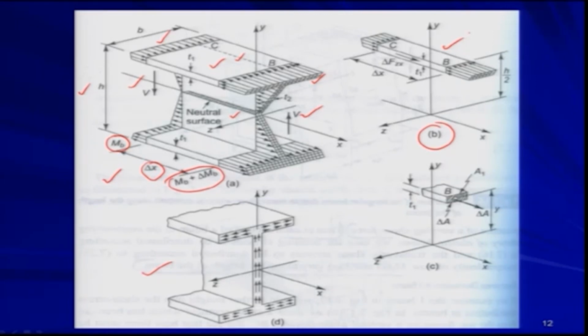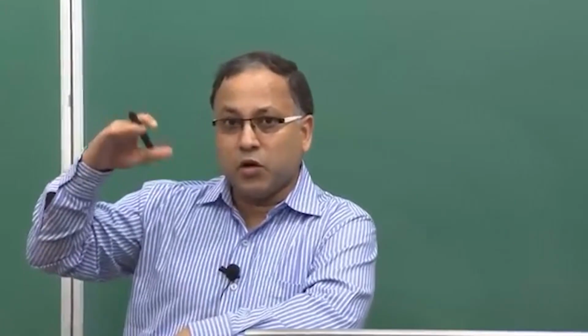Now, there must be a shear force delta Fzx on the positive z face. This cut face is your positive z face. On this positive z face there must be a shear force delta Fzx to maintain the equilibrium in the x direction, which is pretty similar to the previous case where you had delta Fyx on the y plane.